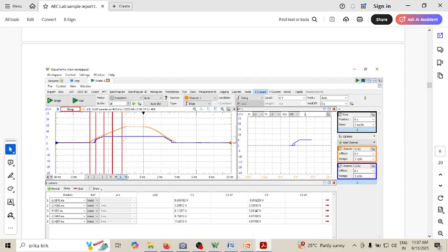So even though we stated that okay, 7 volt is a requirement, this regulator requires 6.13 volts to get a constant 5. You can see this is almost constant here. So that's what is constant here, and the same thing is constant here. This is your XY characteristics or XY plot. So you can just click on this XY in your AD kit and you'll get this. And here we have just put different cursors so that you can see the input and output, which results in this type of graph.